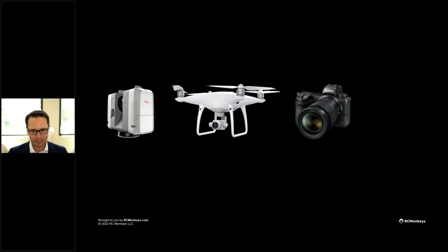And then for ground photography, we're going to need a very good camera. There are a lot of cameras out there that are extremely good for this process, but probably the best value for your money you're going to get with the Sony A7 series, A7 II, A7 III, A7 IV, and especially with the latest versions, you can get very high resolution images up to 61 megapixels.